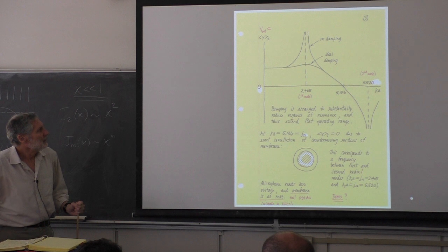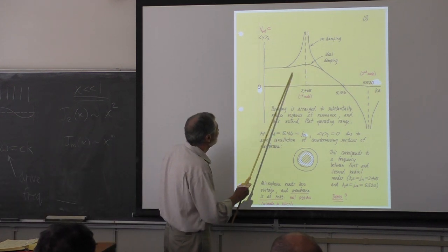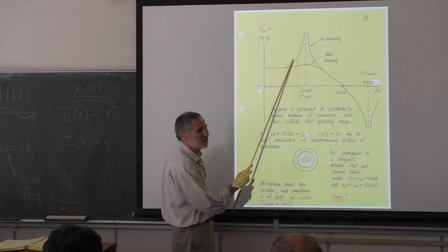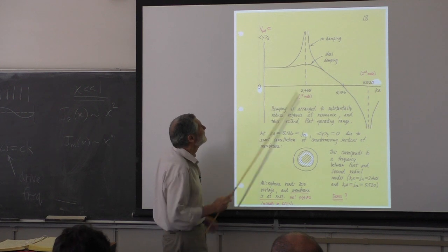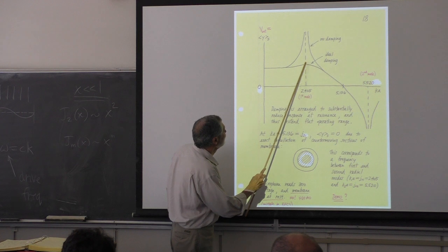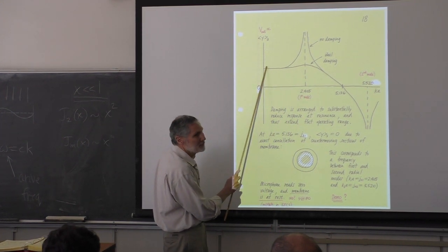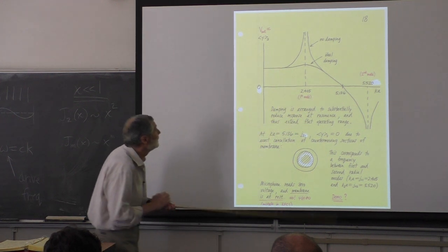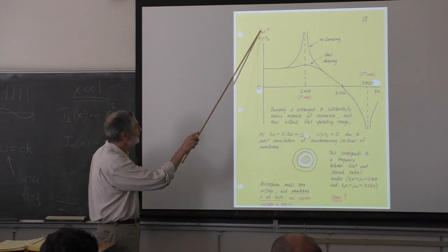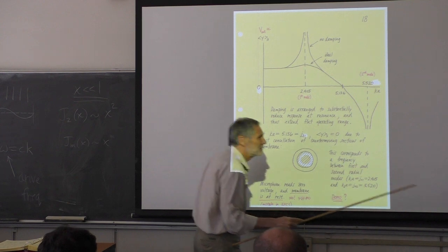So, here's the idea. And again, the scale is really not right here. The typical bandwidth here is set by the quality factor. The typical case is that the resonance is much farther out here, and there's a relatively big flat regime here. But this is what our average Y is, which is proportional to the voltage. That's what we measure. And here we have this flat regime. Again, this conveys it better here.